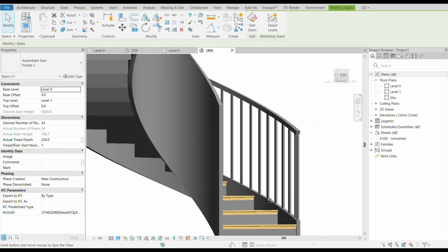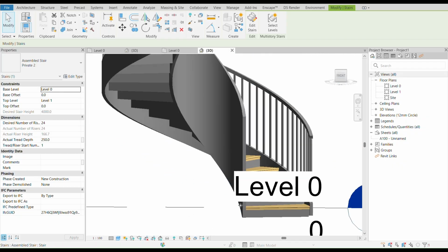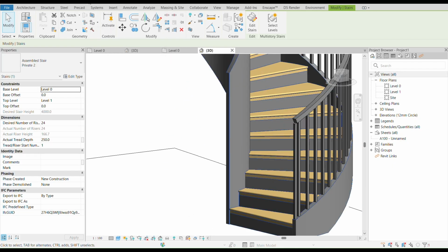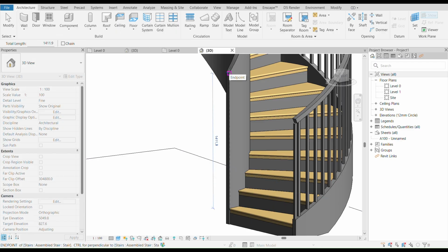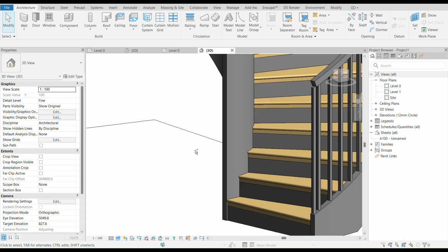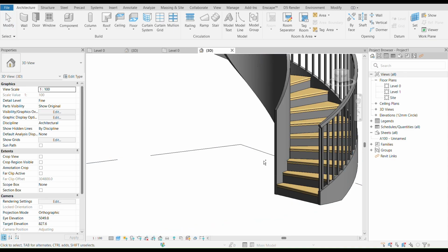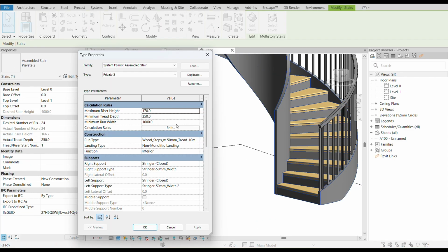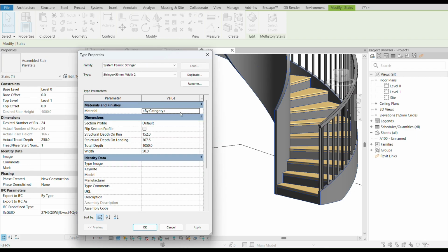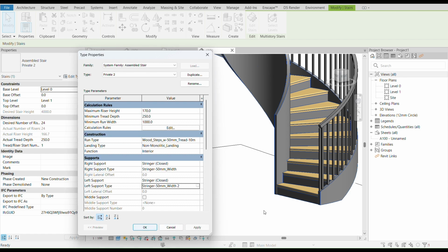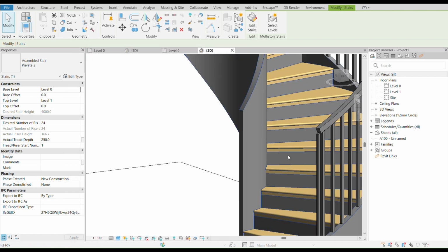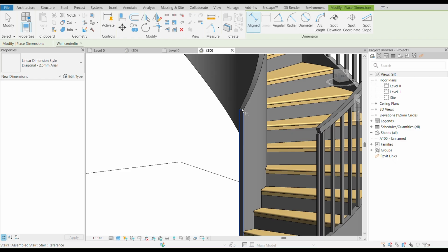and press apply, now if I were to measure this, okay, it's actually more now. Oh yeah. So I guess I have to edit this, but you can just choose your liking the height of this railing that you want. I'll just keep it as maybe 200, I think. Yeah, I think that will work, because I have the stringer depth as 300.